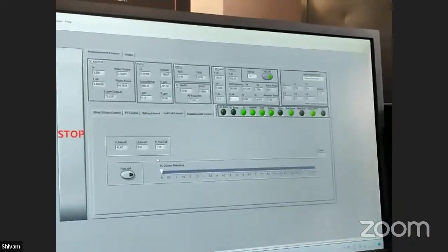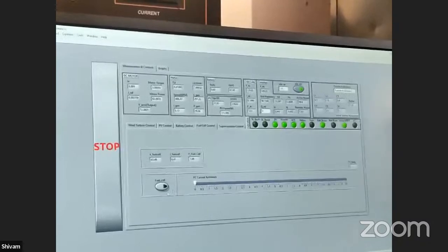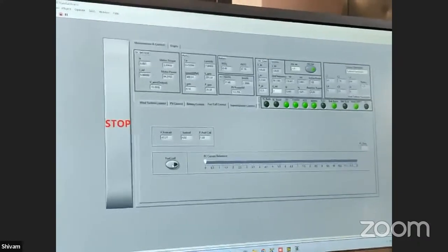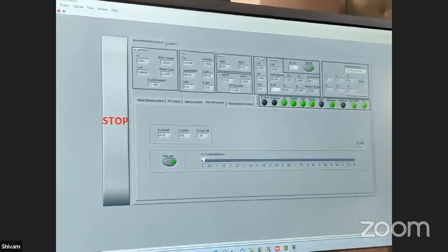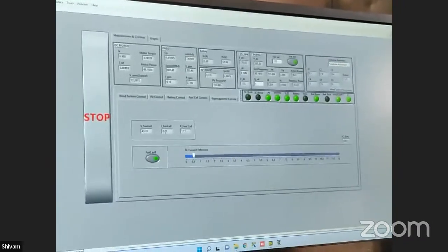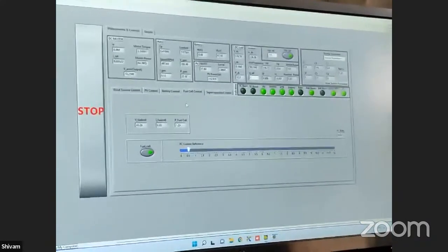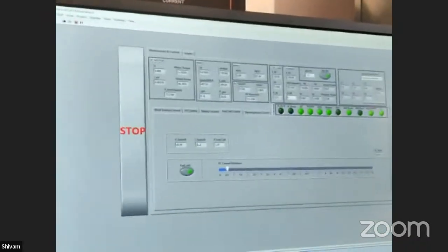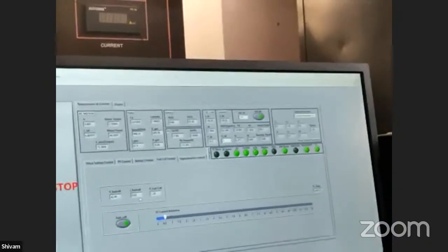We have to follow the same procedure for the fuel cell, but in the case of the fuel cell, you have to be careful because the response of the fuel cell is very slow. Suppose I turn it on and increase the reference current that the fuel cell has to provide. This is going to increase at a very slow rate. Suppose I change it to 0.5. Now you see this is going to take a large time to increase. This is currently 0.03. Voltage buildup is going on in that setup, so it is going to take some time. 0.03 to 0.04, 0.05, it is going to take some time. So for that time, you have to wait. Otherwise, this setup is not injecting power into the grid.